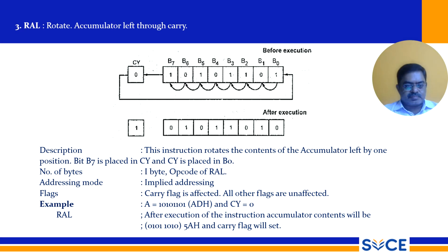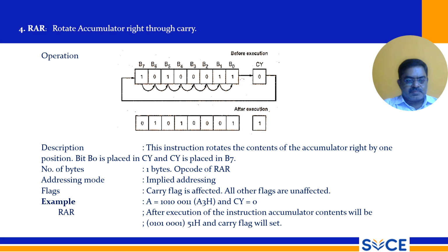RAL, rotate accumulator left through carry. So here, left through carry, the carry is also considered in the rotation, and this instruction rotates the contents of the accumulator left by 1 with carry. RAR is also with carry.